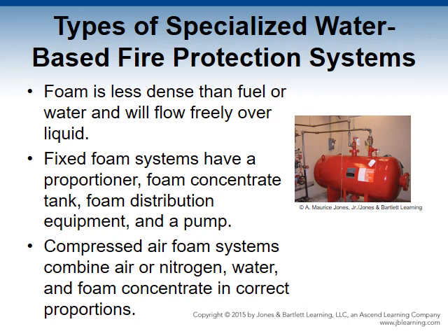NFPA 11, standard for low, medium, and high expansion foam, recognizes a number of different types of foams in terms of the concentration. And they include such things as AFFF, which is aqueous film forming foam, AR-AFFF, which is alcohol resistant aqueous film forming foam, film forming fluoroprotein foam, protein foam, fluoroprotein, medium expansion foam, and high expansion foam. So again, depending on the hazards and the cost will dictate what foam you're going to use.